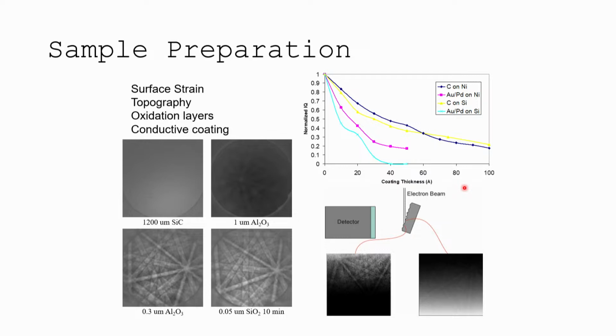All right, the other thing that I'm showing here is this surface roughness. So sometimes you can get good diffraction just off a fracture surface, something like this, especially if you have cleavage. But then you start getting these little cleavage planes, these bumps that you'll get in the surface sometimes. And you'll get reasonable diffraction off some, less off others. But what it's showing is you have a different orientation of the place where your beam hits the specimen. So instead of hitting the specimen at 70 degrees tilt with a nice surface, locally your surface is maybe at a 50 degree tilt or at an 80 degree tilt. So you get diffraction either at the top of your phosphor or at the bottom of your phosphor, and it affects your pattern quality a lot, of course.